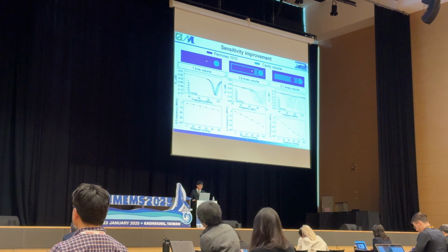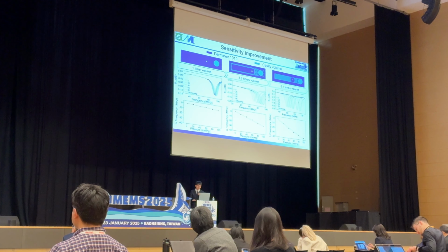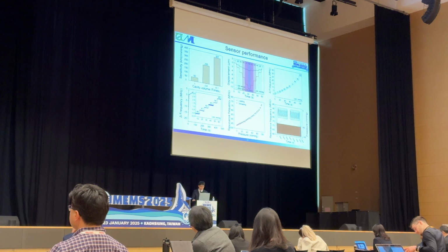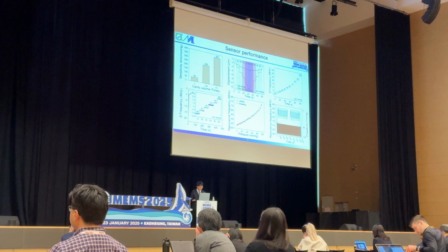We can see that when we apply the same pressure to the sensors, the change of frequency increases according to the increase of the cavity, which means our sensor sensitivity will be increased. Then we test the basic performance of the sensor. First, as we already introduced, is the sensitivity related to the cavity volume.